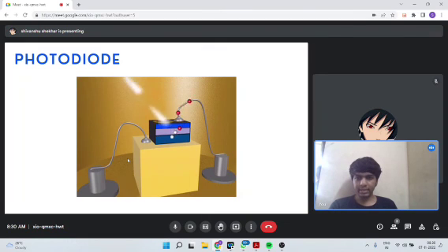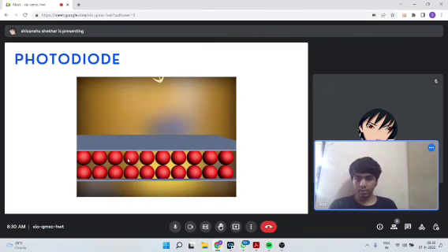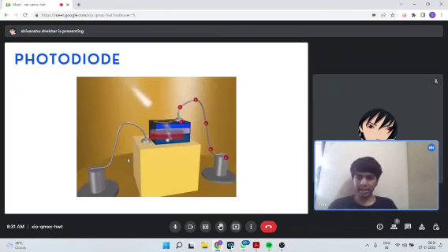So when light is incident, we see electrons moving out in the circuit. The photon leads to excitation and additional energy, causing the creation of electron-hole pairs. The holes remain stationary while the electrons start flowing in the circuit. This causes the flow of current, leading to a voltage difference and thus some electric power being generated.